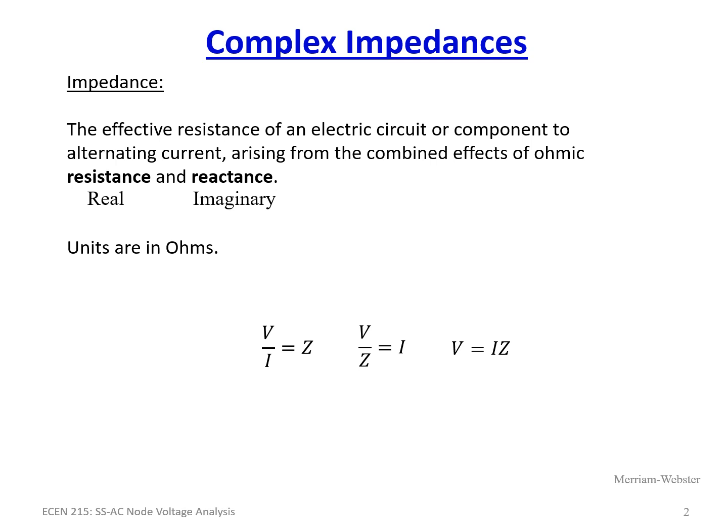Ohm's law still applies. It's just that now, instead of R, we're going to use the letter Z to represent that this is a complex impedance instead of just ordinary resistance. So we have V over I is Z, V over Z is I, or V is equal to IZ. If you've learned that equation and have mastered it, then you are all set. You just have to replace the letter R with the letter Z.